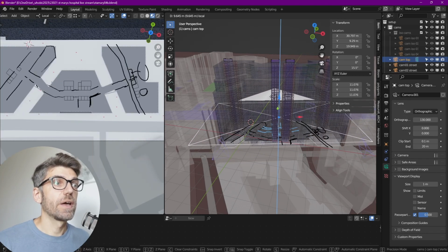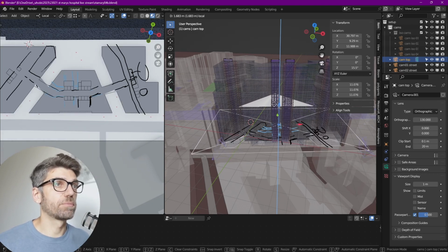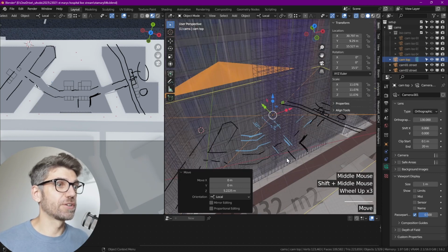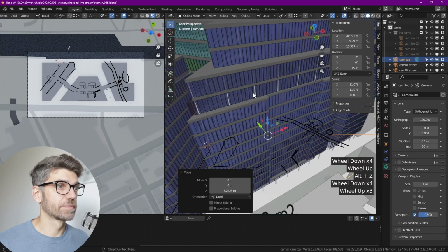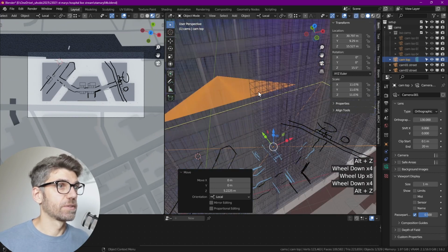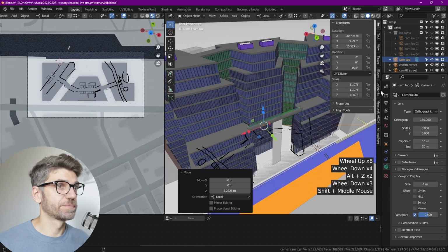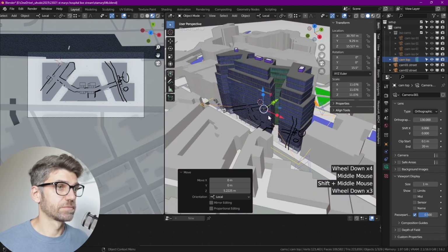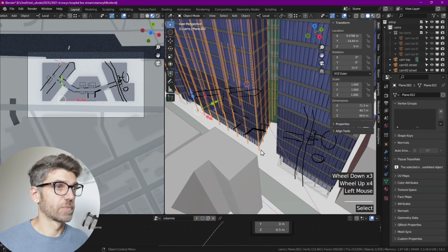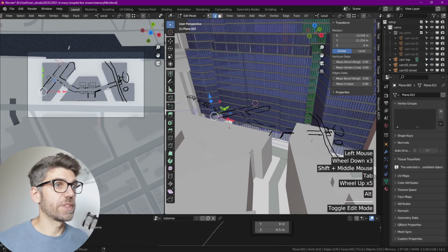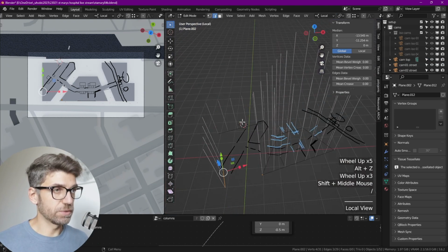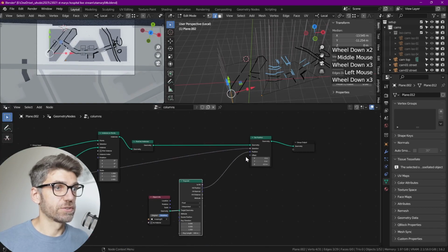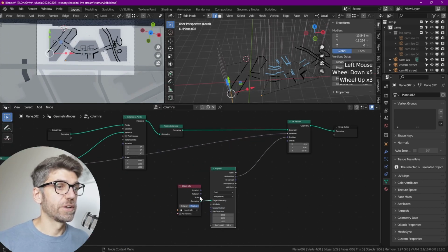We have to do a similar thing with the columns if we want them to show up. So how do we do that with the columns? We have to basically go and extrude them again. So where have we got our trusty columns here? There's a set over here. So with that one, let's go and just isolate it so I can see it a little bit clearer. These ones are the ones that are extruded.